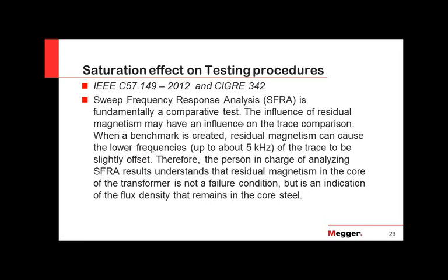Now we go to the standard for sweep frequency response analysis, C57.149, and of course, CIGRE 342. And the most important thing that you have to remember for sweep frequency response analysis is that this is a comparative test. You need to be able to repeat the same condition testing as it was tested before, or the way you have your previous, your original signature of the transformer.